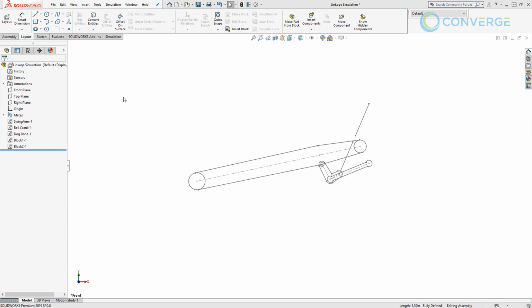But today, and for the last topic, what I want to talk about is using Sketchblocks for motion in an assembly. There's a lot of things that we can do with them in a part, such as the kinematics, but in an assembly, we can actually have a motion study. We can apply a mass to the sketch block. We can apply things like forces and springs and dampers and motors. So there's a whole other level of things that we can do with these.